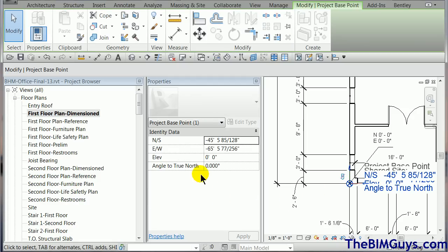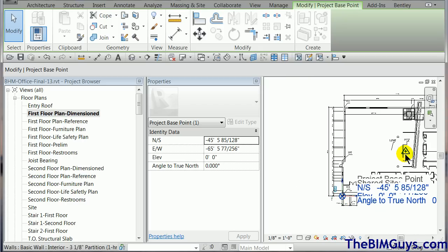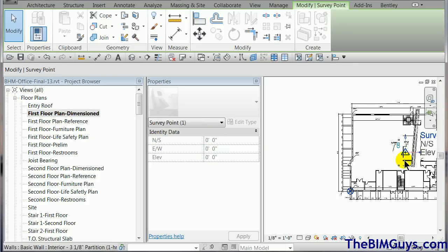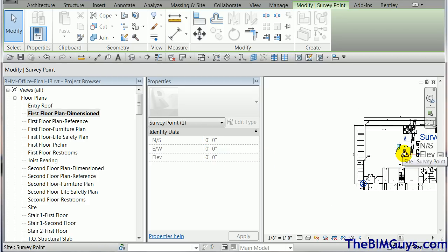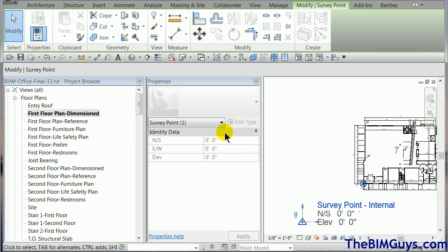You'll notice that it says in relationship to the site, here it is, -45, -65, in relation to site. Now here's where it gets interesting. I'm going to pin this one back so it's happy now. Now I'm going to go up to the site. Now when I click on the site, you do not unpin it. See that note? See it's 0, 0. So I'm going to take my 0, 0 and I'm now going to click it. I'm going to move it from here to here. Let's put it out in the yard, right? Now, see, that is true 0, 0 for my project.